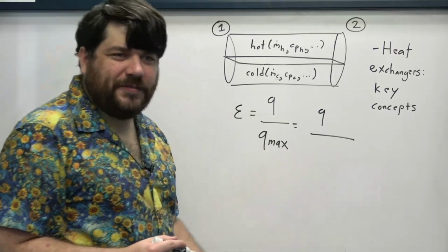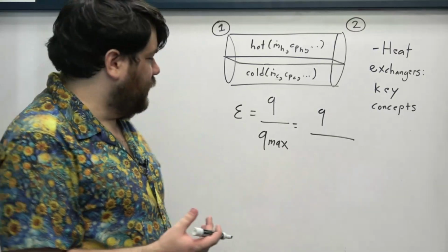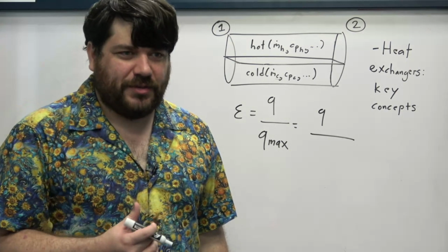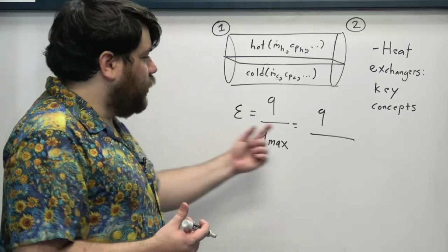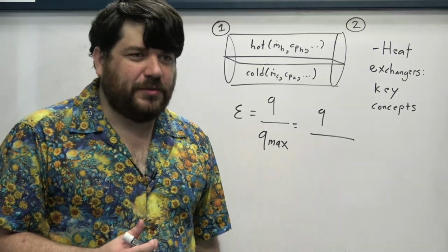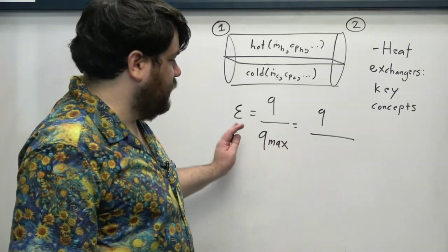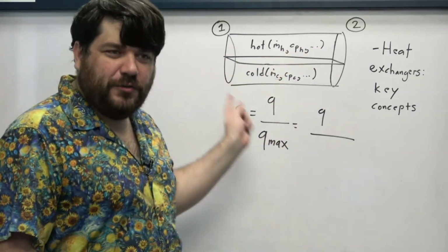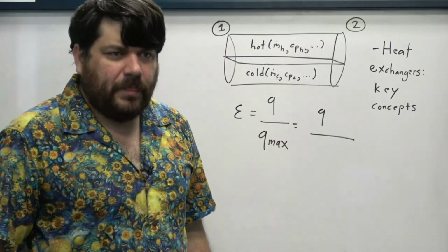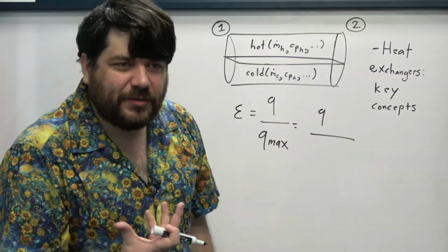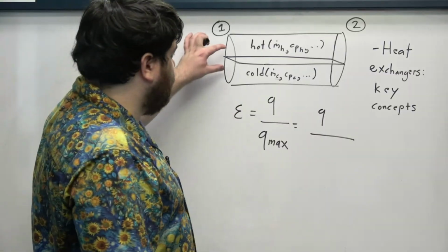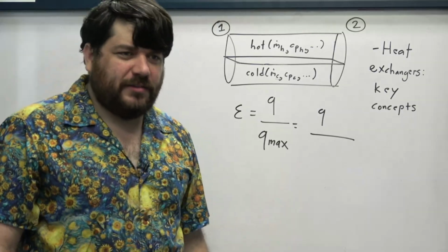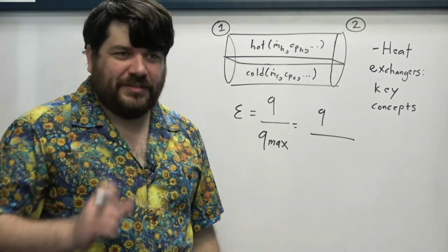We know that in internal flows, this Q is the product of a heat capacity rate and a temperature difference. And so what is the largest temperature difference that we can possibly use in the analysis of this particular kind of problem? What is the largest temperature difference that shows up anywhere in here? And although this is not a physical temperature difference, it's not a temperature difference that happens between overlapping pieces of liquid necessarily, okay?